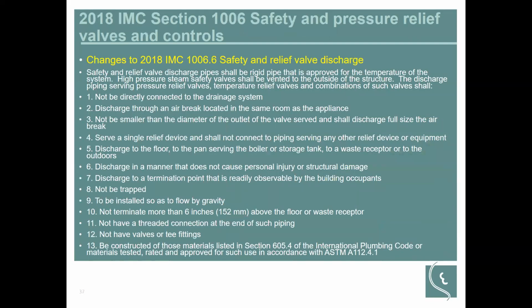As far as the, there's a lot of new stuff coming to the IMC, specifically for safety and relief valves, making sure that, because these are safety and pressure relief valves, they're discharging in a safe manner. So these are 13 new points to it. Won't read them all to you, but this is a very large change, again, specifically related to safety here in the IMC, 1006.6 for safety valves. A lot of these are similar to other requirements that have been there in the past.